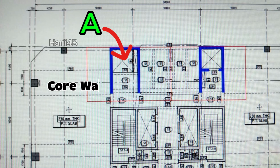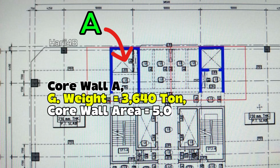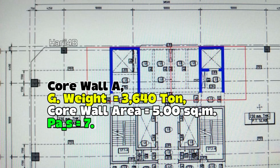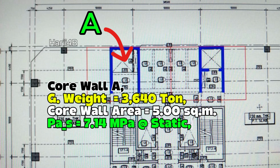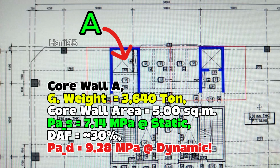For core wall A, the gross weight carried is equal to 3,640 tons divided by a core wall area equal to 5 square meters. Hence, the axial pressure shall be 7.14 megapascals. Note that this is for static condition only. When an earthquake occurs, we increase the weight with a dynamic amplification factor of at least 30%. Now, the axial pressure is equal to 9.28 megapascals.